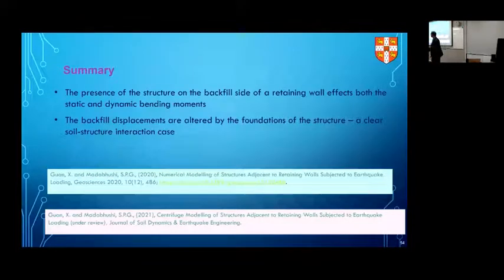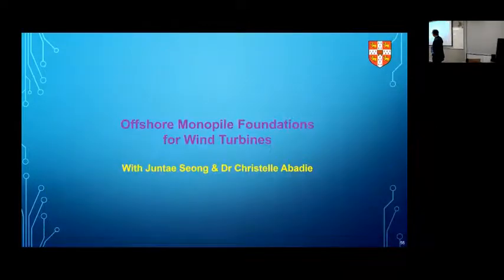So the presence of the structure on the backfill side of the retaining wall will affect both the static and dynamic bending moments that you can expect. But the displacement field in the backfill is completely altered by the foundations of the structure. And that is the lesson we learned from this particular work.